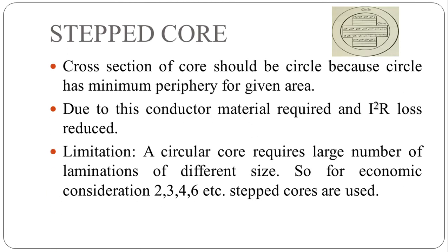So this is the diagram of a two-stepped core. Here in this two-stepped core, laminations of two different sizes are used. Generally 2, 3, 4 or 6 stepped cores are used. So this is the concept of stepped core. We use a stepped core to save the copper material.